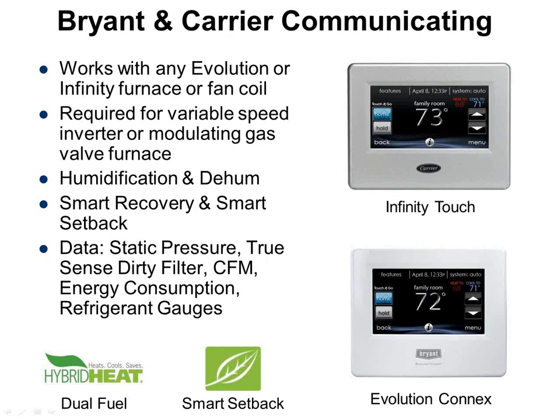So in terms of Bryant and Carrier, I'm going to talk about them together. I think most people on this webinar realize that Bryant is part of Carrier, so they make a lot of stuff that both of them have. Their main internet thermostat is really not even a thermostat. It's a communicating control. So what that means for starters is that it doesn't have your normal thermostat wiring, you know, G, Y, W, etc. Instead, it has a communication signal that goes from the stat to the furnace, and data is passed that way, and the furnace is really making the decisions on what to do.